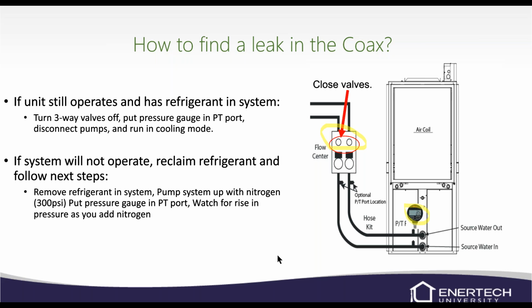The coaxial heat exchangers, for one, they can handle freezing a little bit better, and sometimes it'll just be a real small leak and it's really hard to find. So a lot of times that's due to maybe there's a problem with the coax and it tends to etch away at the heat exchanger slowly over time.